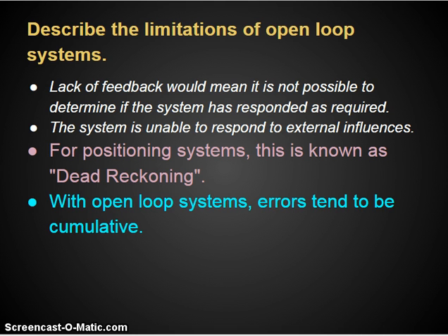While that sounds great, there are many variables that can affect that. One of the motors can be underperforming. So if you have a skid steer system, what would happen is the drive system would take it in a curve. It wouldn't go in a straight line because one motor is going slower than the other motor. Or there could be obstacles in the way, so it could run into something and just sit there and drive against it for a full second and wouldn't actually travel in a straight line for 1 second. Or there could be something on the driving surface that causes one or both wheels to slip.